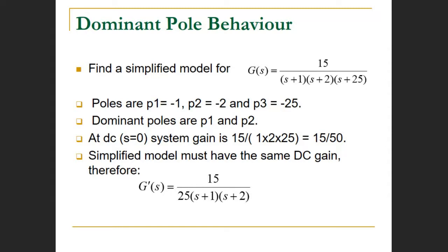We look at -1, look at -2. So therefore, let us ignore -1 because it's the closer one to the imaginary axis. So clearly that is a dominant pole. But let us look at P2. P2 is -2. And when you look at -2, 10 times -2 is -20.